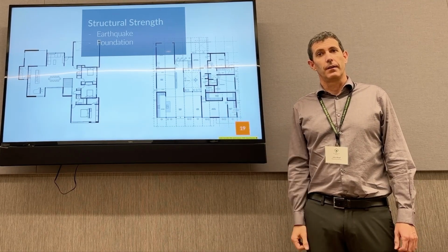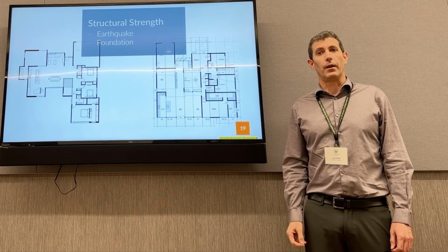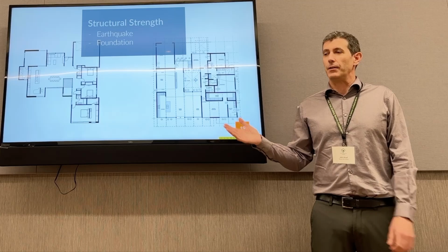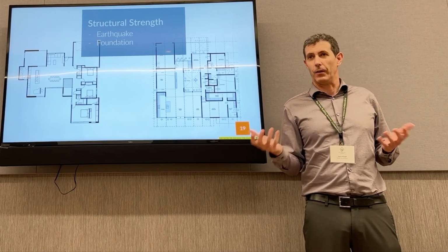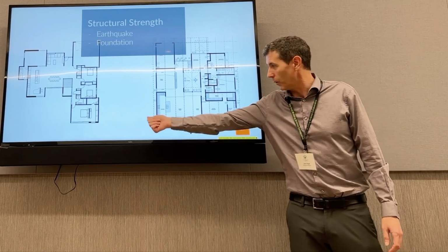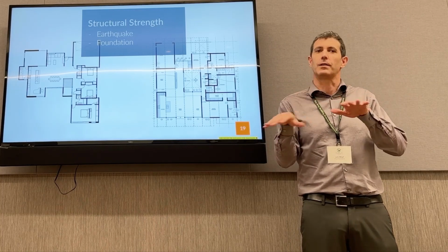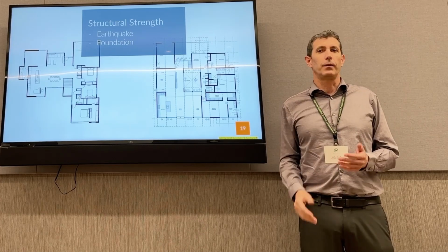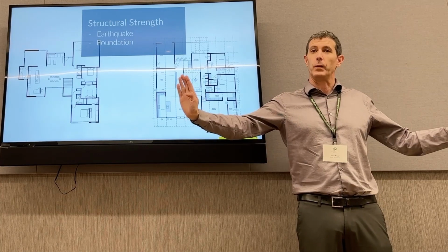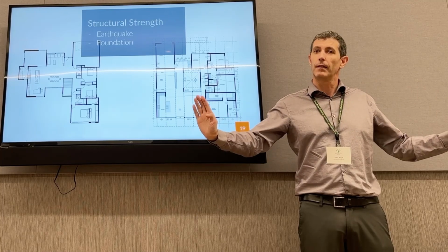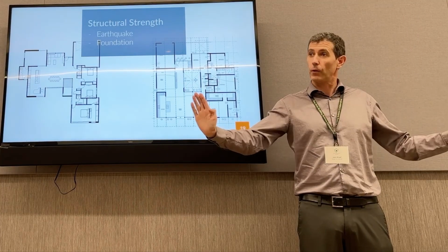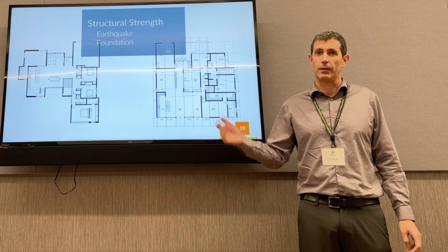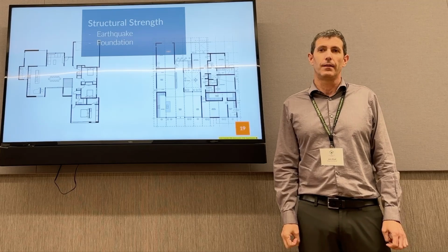That's a structural change? That's right. Well, the glass is not considered structural, obviously. No, right. But if you don't weaken it, you don't have to improve it. This is a flexible diaphragm structure. This is all wood construction. You only need to upgrade on the one line that you weaken, and you have to weaken it by 10%. And then you have to upgrade that line to fully comply with current code in terms of the shear, specifically shear, which is the element that governs those lateral designs.